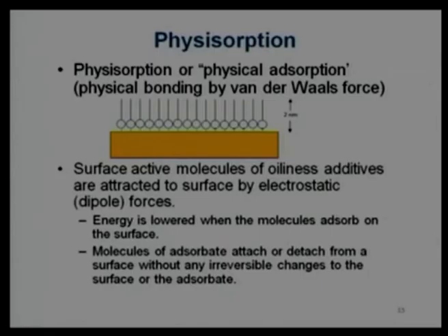In reality, every metal is subjected to boundary lubrication, even in the absence of liquid lubricant or boundary additive lubricants. That is a natural phenomenon. If the material is open to the environment, it will get oxidized and a thin layer will be made, and this thin layer will not have very good chemical affinity towards the other metal. So, it will give an interface with much lower shear strength.